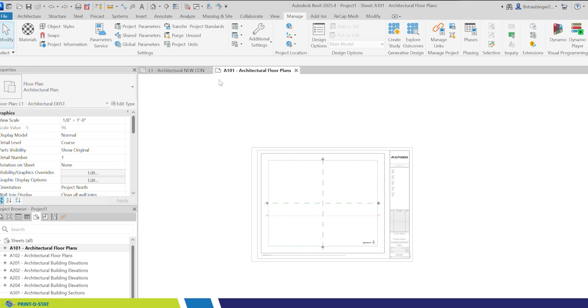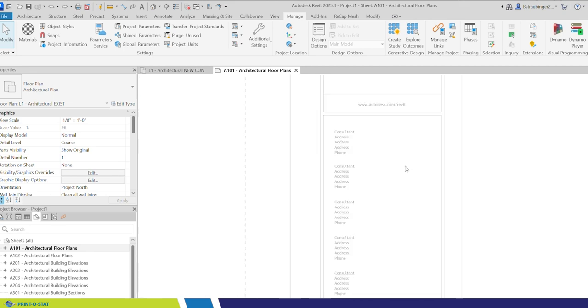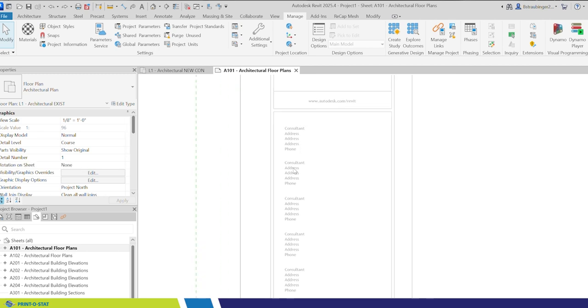So I thought I would take these 5 or 6 lines here, and show you how to fill those in very nicely and neatly in project information right here. It's on the Manage tab, project information. I would like to have these filled in automatically on every sheet in my project. So I created some shared parameters that go to the title block.